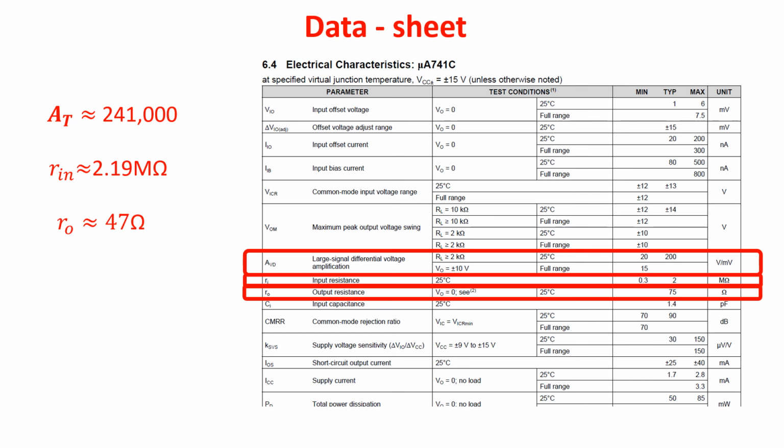All this shouldn't surprise us because we made some assumption about betas and early voltages, but these values depend on fabrication parameters subject to the uncertainty of the production process. Moreover, about the output resistance, we made the arbitrary assumption of an output current of 2.5 milliamps.